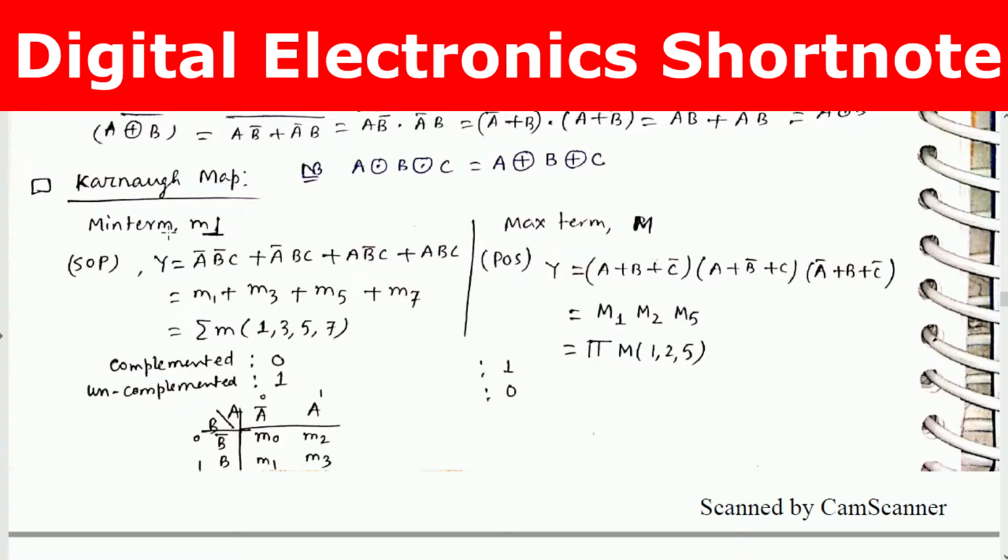Karnaugh map. It's a very interesting and important thing. So first, let's know about min term and max term. Min terms, we get sum of product, SOP, and this is product of sum. Sum of products means, look, these are the products and we are taking the sum, and these are min terms, M1, M3, M5, M7. 0 0 1 means 1, 0 1 1.